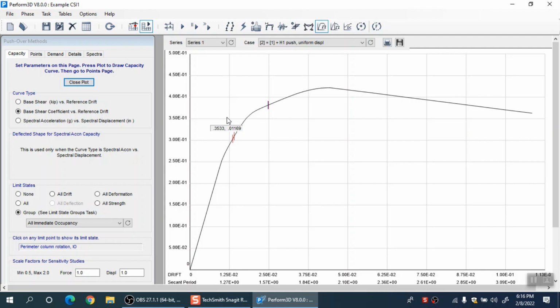There can be several pieces of information which you can get from this curve alone. But for the purpose of seismic analysis, you need to have an idea about the peak displacement against a certain level of earthquake, and then you bring that displacement here, put it in the same graph, and convert the results into seismic analysis results, right.